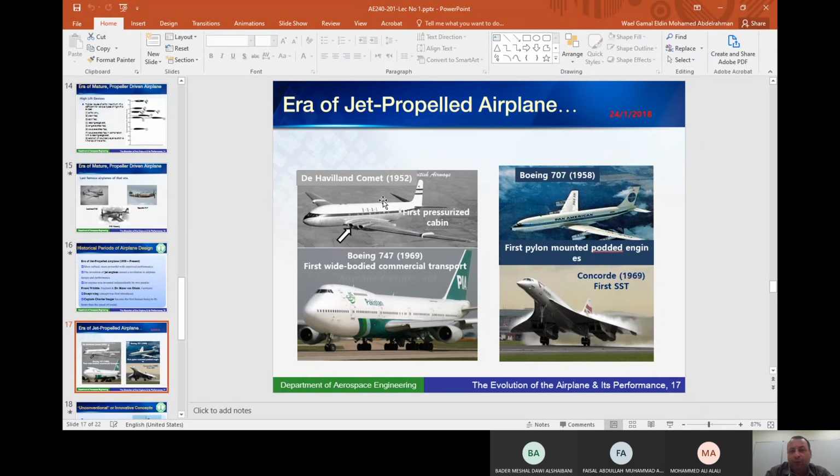When the aircraft goes up, you pressurize, you fill it with air. Then when it goes down, you depressurize, you take the air out. Pressurize, depressurize. That would put a lot of alternating stress on the skin of the aircraft. And if you have a crack or a notch on this skin, it will just get bigger and bigger until it causes catastrophic failure.